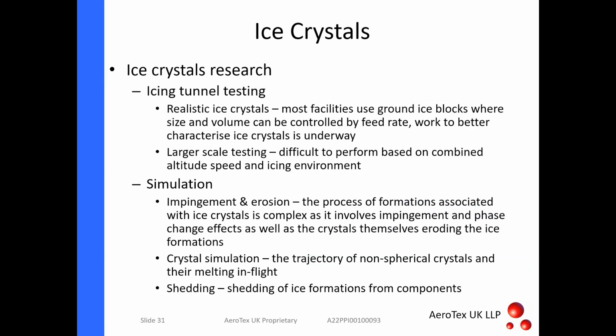So some of the challenges is realistic ice crystals. So most facilities have got a big block of ice that they grind up, and by controlling the feed rate and the spacing of the blades, they can get different ice crystals, but they're not atmospheric ice crystals. TU Braunschweig in Germany have actually got a chamber where they naturally grow crystals, but the issue is that they've probably got 2 or 3 seconds of running time before the ice crystals run out. And also the issue with larger scale testing is how can we achieve that?